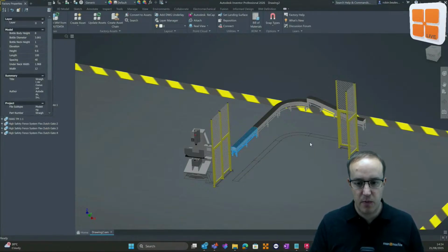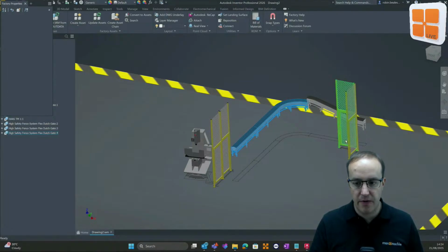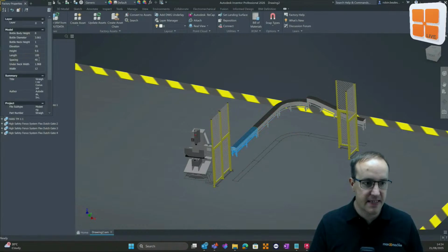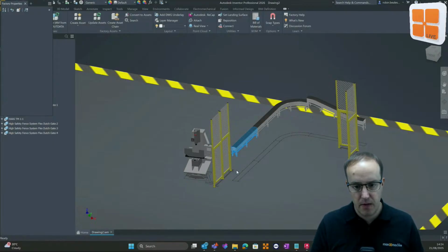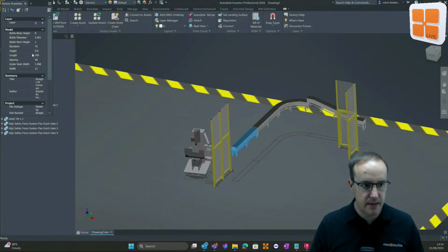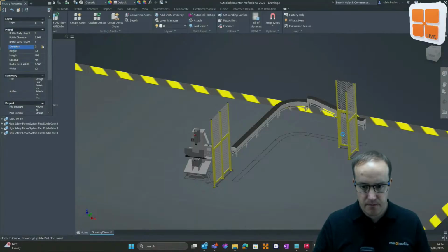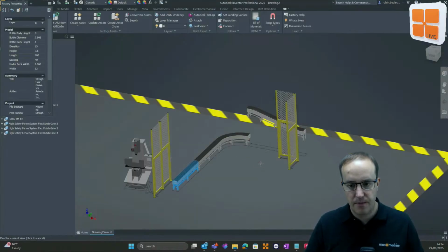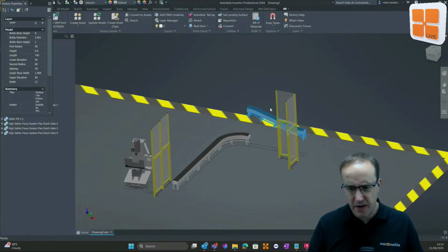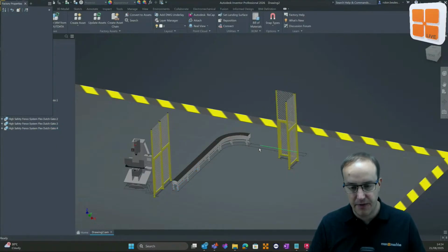And you can see in Inventor we've got our own controls. So I can grab these three components and I can move them around. So using the factory properties, I could grab this one and I could say that I want to put the height on here as 0. Oh sorry, the elevation as 0. And I can move the elevation down and set that onto the floor. This one I've decided I don't want, so I'm going to delete it out of the design.